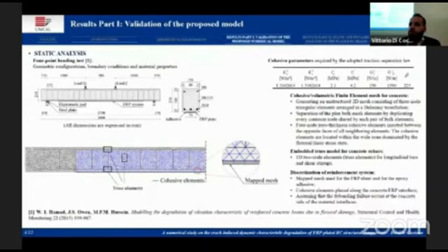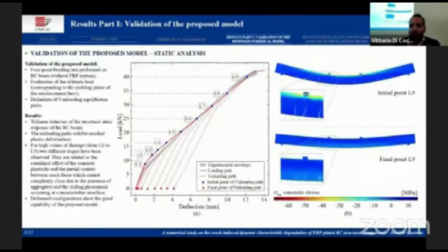Our numerical simulations involve a 4-point bending test performed by Amado and co-authors in 2015. Preliminarily, we analyzed a reinforced concrete beam without any FRP reinforcement system. We evaluated the ultimate load, and we defined 9 unloading levels as a fraction of the failure load. We can see that each unloading path exhibits residual plastic deformation.